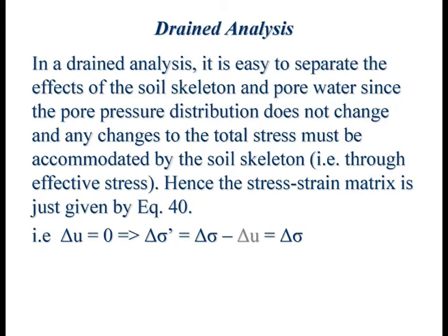Right, this was the last slide I showed before lunch, and it's on drained analysis. To recap, in a drained analysis there is no issue about the pore pressure because the pore pressure is separately calculated. It's well known. If it's hydrostatic, it's known. If not, it is calculated either by seepage consideration or something like that.